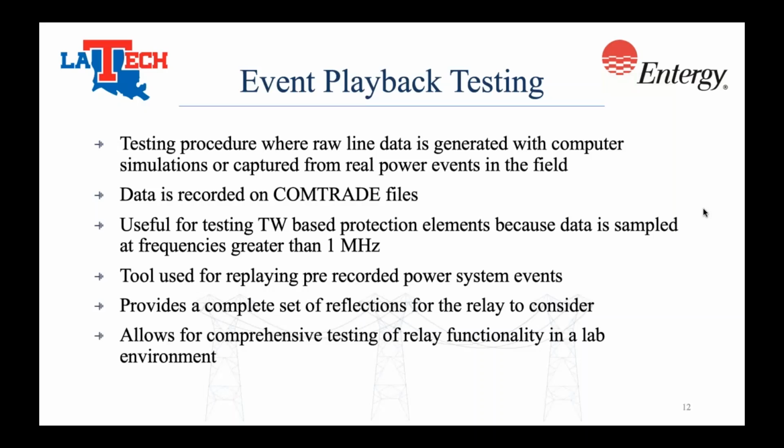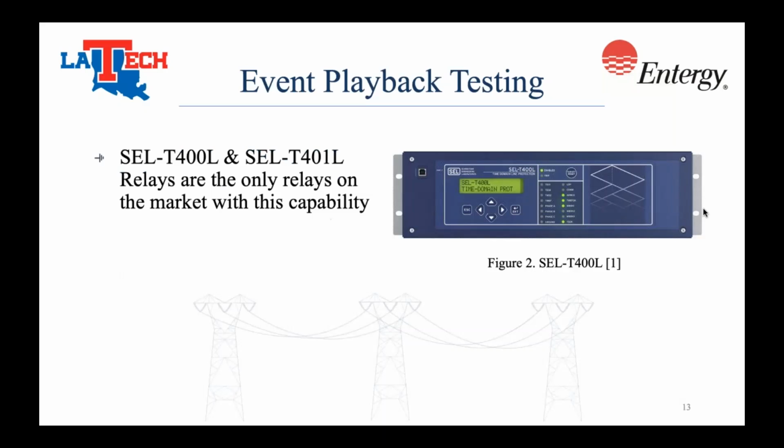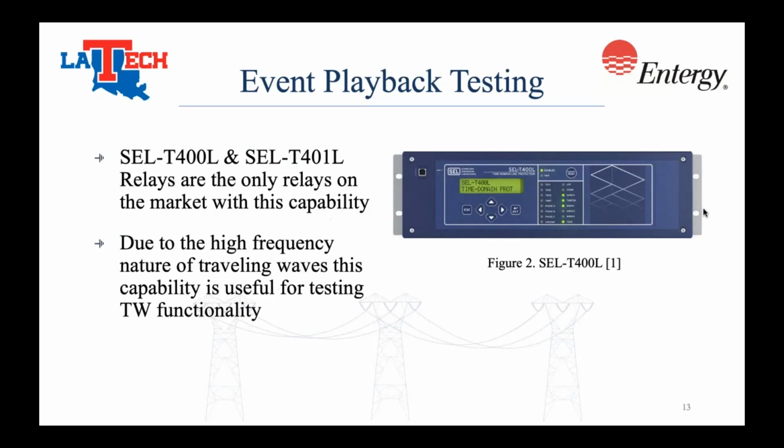This method provides a complete set of reflections for the relay to consider, and it is used for design and testing traveling wave-based protection schemes. The SEL-T400L and the T401L relays are the only relays on the market with this capability. Due to the high-frequency nature of traveling waves, event playback testing is a very useful feature on traveling wave-based protection relays.